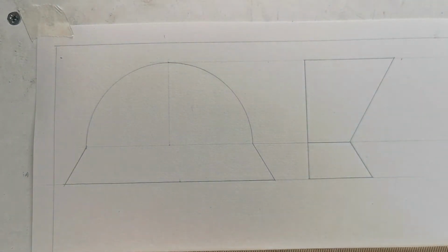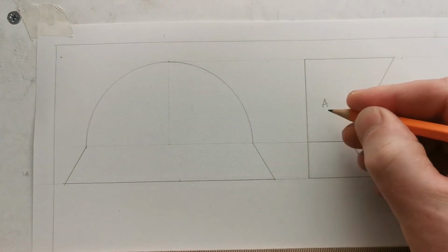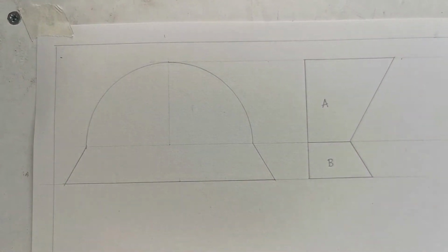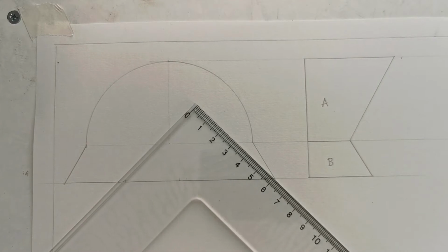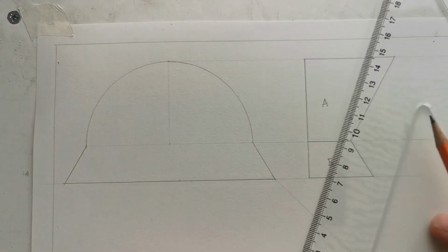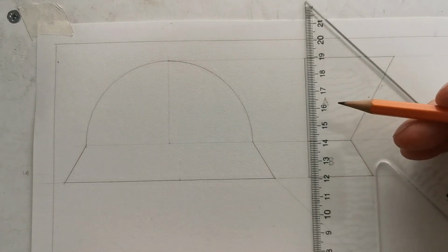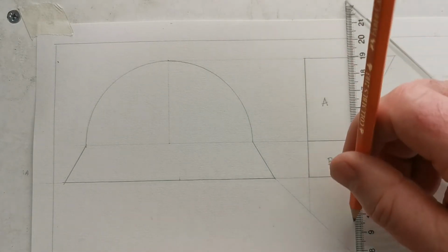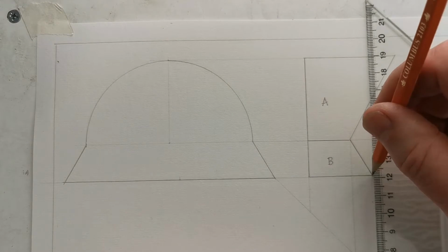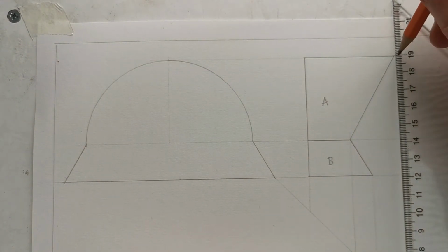Okay, so here is section A and here's that surface B. Now, the question asked there, so to draw the elevation, draw the end view, then draw a plan. So I'm going to just set up my 45-degree line here to project. So again, not a lot of lines involved in this. As I said, a nice question because it does test the understanding. So I'm going to bring over my distances here.